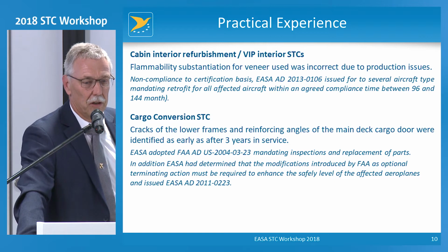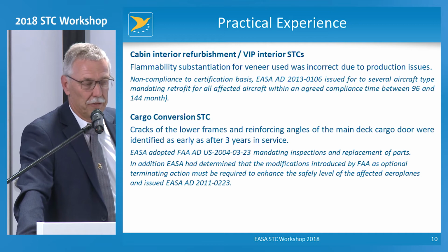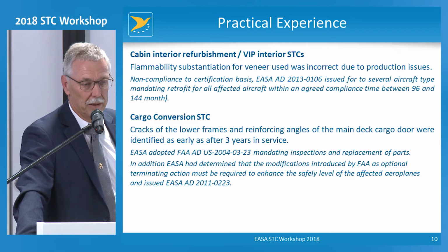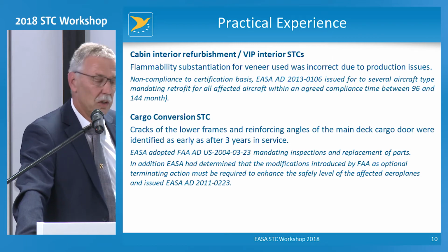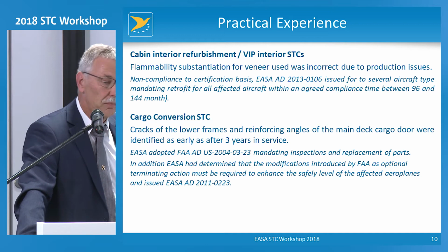retrofits with a very long compliance time of up to 12 years even, because the risk is not too high. It was not too much material that was wrong, and the probability of a single aircraft to have hazardous events related to that was low, so the compliance time was agreed to be 12 years.